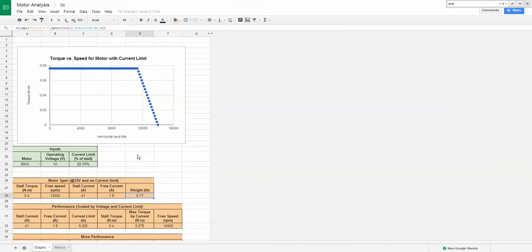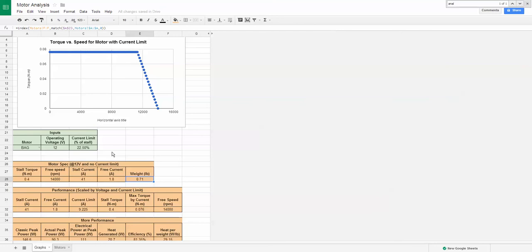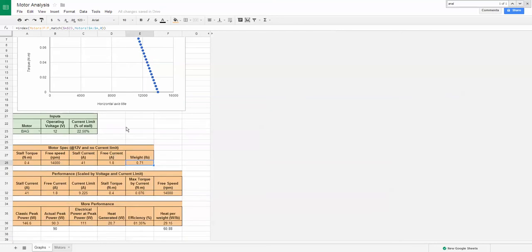Aside from the fact that I don't like the 775s because of their failure with those windings burning, with the insulation failure, the fact that it is essentially comparable power to the 550 at twice the mass makes it a much more durable motor.